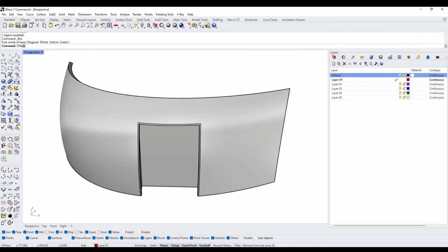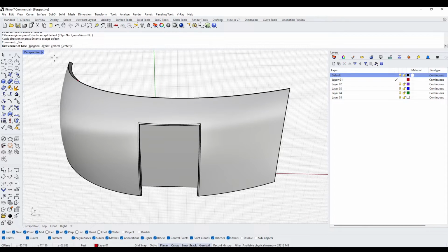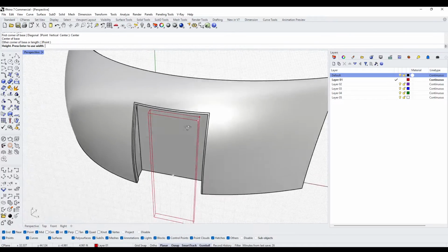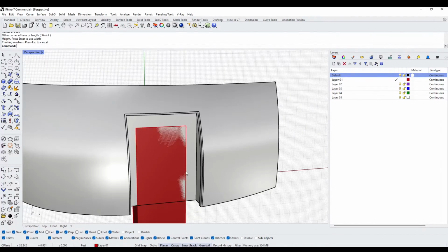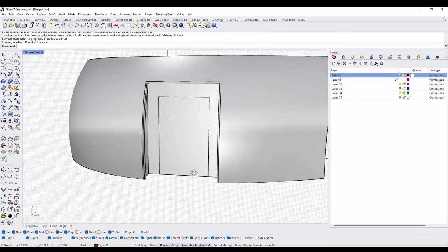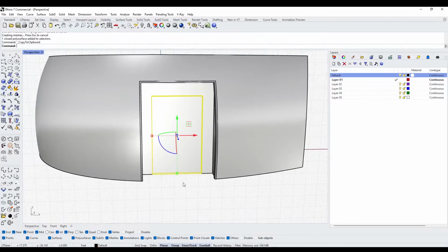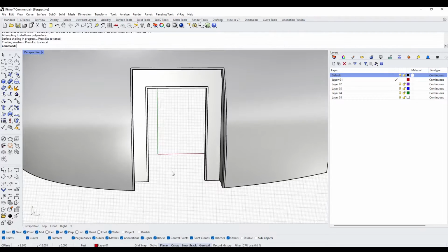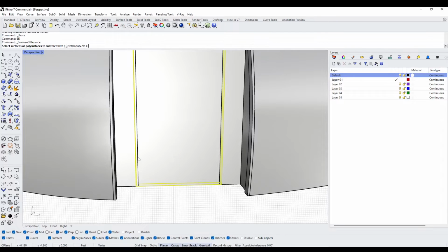How? Well, I like to use C-plane, surface, then using a box relative to the center point, and do the same thing here. So this one, copy, Boolean difference, this one, paste, and then Boolean intersection. Copy, then shell, then paste, and then Boolean difference, this one.